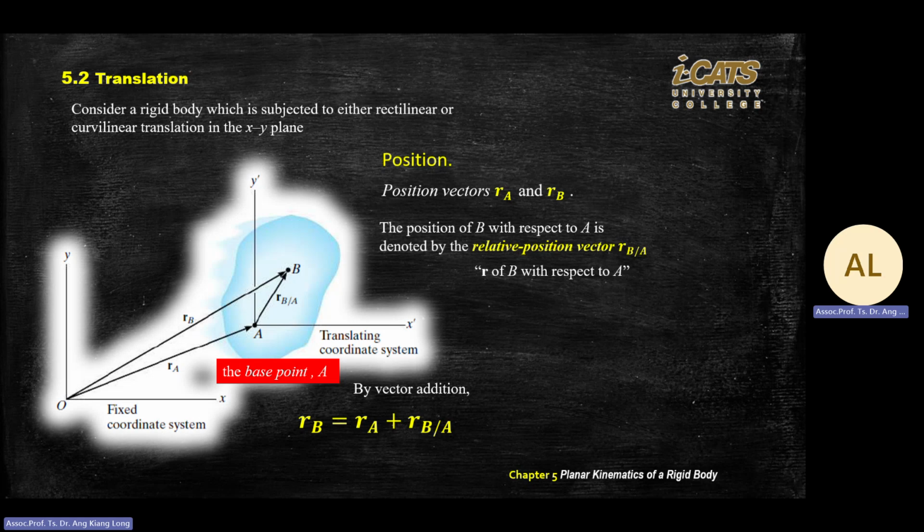But every time you solve a chapter 5, 6, 7 question, you need to draw the vector diagram or the position diagram. Okay, first you need to identify where your reference point is, where your observer is, your stationary point, where you look from. You need to find the O point. Next, you need to identify the moving object mentioned in the question. On the moving object, there are points of interest that are mentioned. In this case, on the slide here, you have two points of interest, A and B. They are on the object.